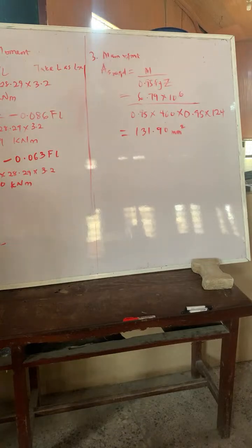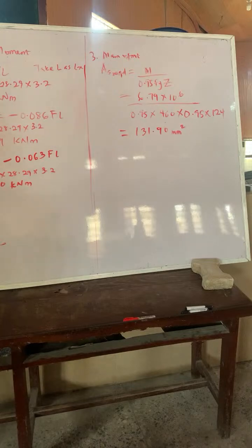Your moment now is changing. Let's calculate for your force. wLx is your force. Then you now check your table 3.12. You get your moment formulas there for each span you are told to calculate for. You are told to calculate for this, and this. You don't add everything. You know it's different moments. So you now calculate the reinforcement for each of these.